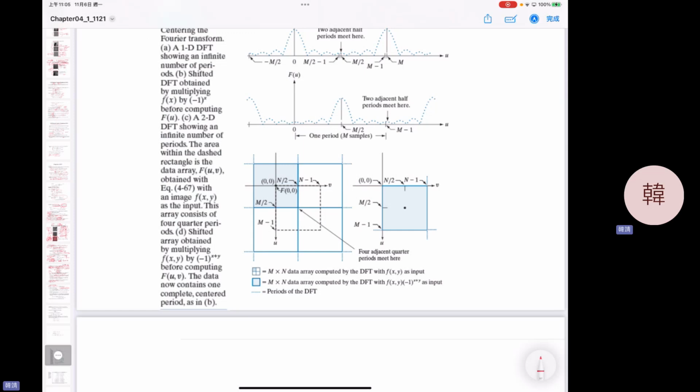So we need this to be the size of this one, because of the periodic property of your Fourier transform. You want to make sure no overlapping error occurs during your process in the Fourier domain. So we extend F to this image, and we call it the extended zero padded image on your outside. Actually, you can do different padding processes and see what the result is.